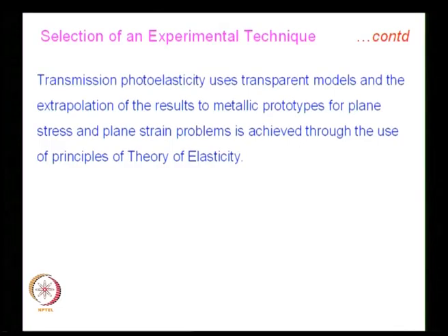But from the point of view of selection, if my problem on hand demands stress analysis interior to the body, then I would find out whether I could go for 3-dimensional photoelastic analysis, because a certain class of problems you can handle, and a certain class of problems you will not be in a position to handle. Transmission photoelasticity uses transparent models, and the extrapolation of the results to metallic prototypes for plane stress and plane strain problems is achieved through the use of principles of theory of elasticity.